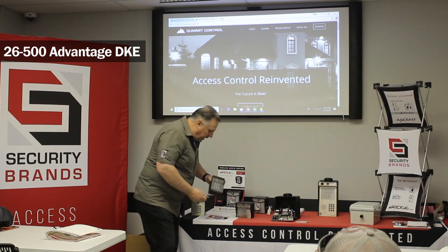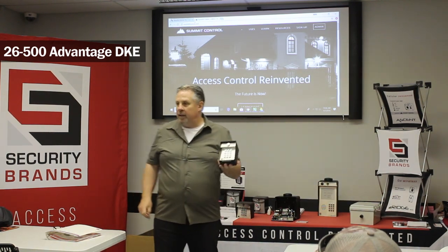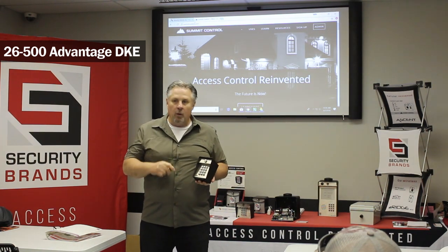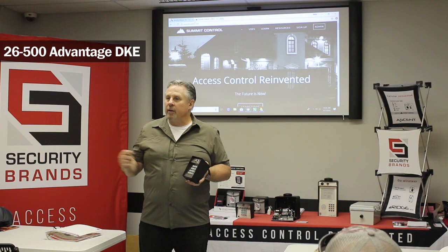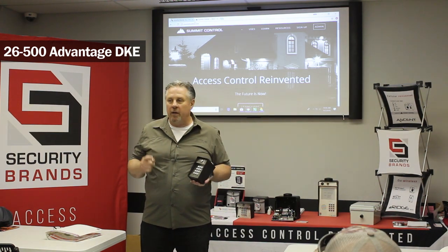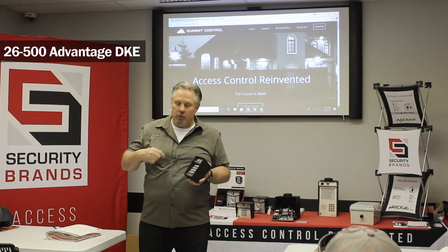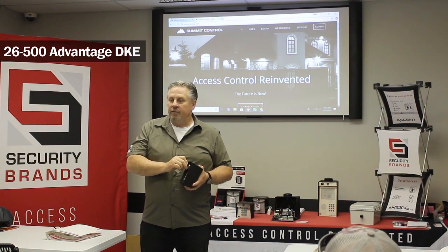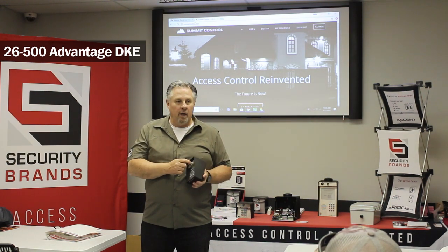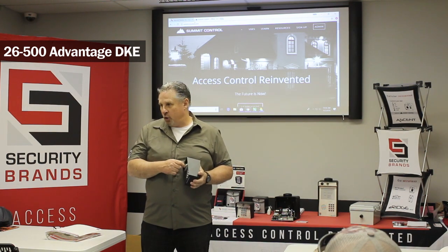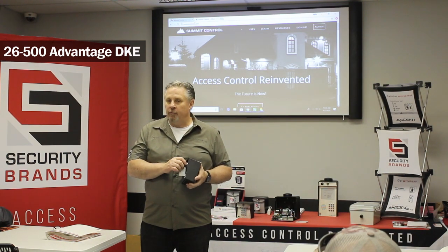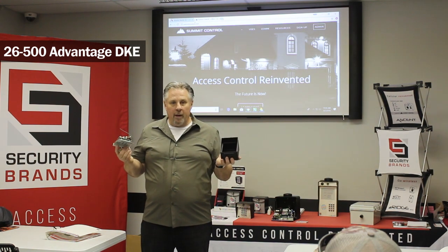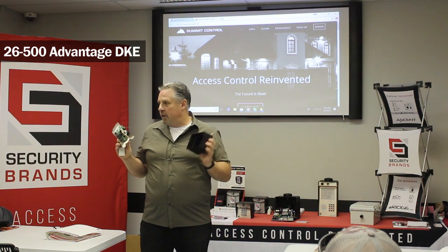My next one up is my DKE. It stands for Digital Keypad Economy. Economy, knowing the name of the product, kind of tells you what it does. Digital keypad low power, digital keypad economy. My economy keypad is a 500 code keypad with a night light, 2 relays, and a latch code. Very powerful keypad for what it is. A very simple keypad. One way I make it economy is by removing the hinge.